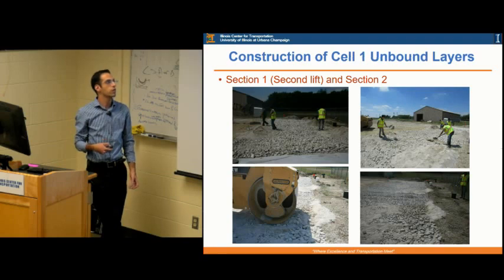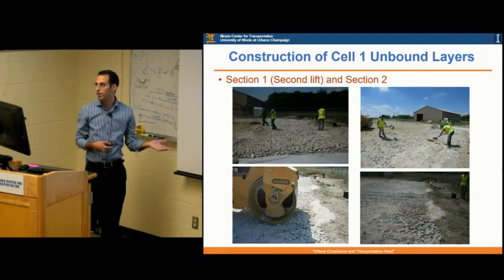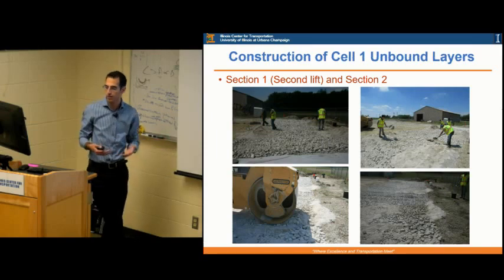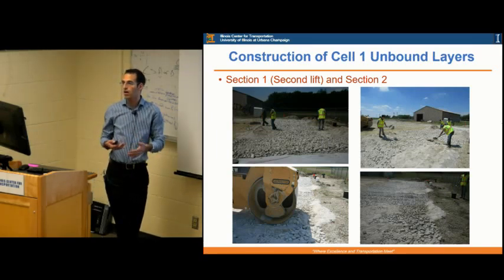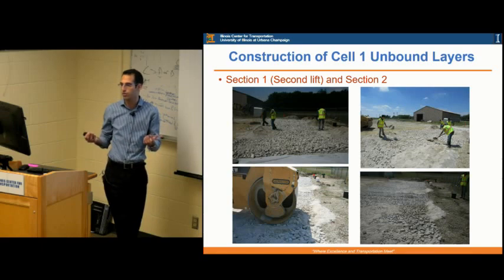And of course, we were doing it this way manually in the field in this experiment, but for future applications, the way this should be done is to spread the quarry byproducts more uniformly from those salt trucks, or using spreaders, and then we have a big vibrator roller following it and shaking those quarry byproducts inside.